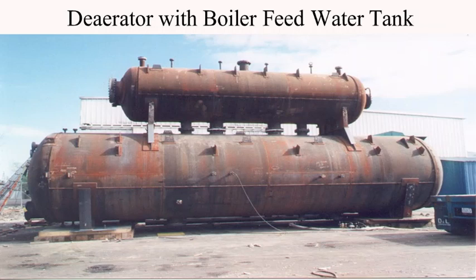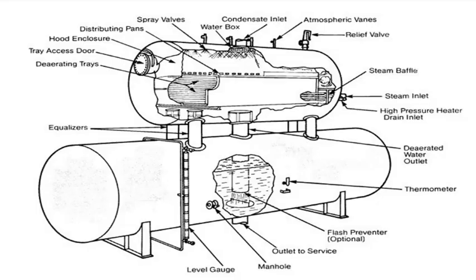boiler feed water tank. Within the feed water tank also we have heating steam supplied from extracted steam, as well as there is some pressurizing steam supplied from PRDS steam supply system. So together heating steam and pressurizing steam, there is a continuous steam supply within this location of boiler feed tank. There are also several recirculation lines as well as drain lines.